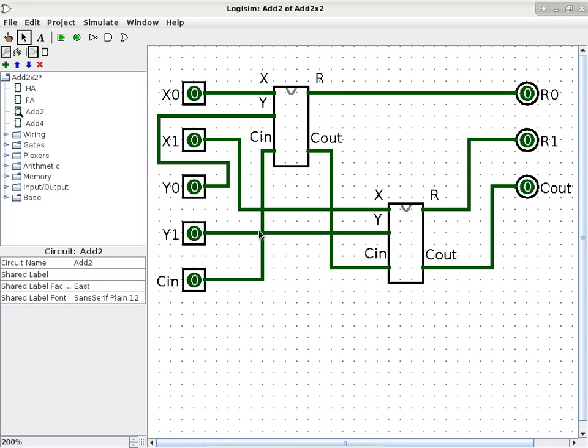If it takes 2 nanoseconds for one full adder to settle down, and you have a 64-bit adder, then you will need 64 times 2, which is 128 nanoseconds for the entire number to settle down to the correct value. So what you're saying is the more of these components that you have, the more delay you have.